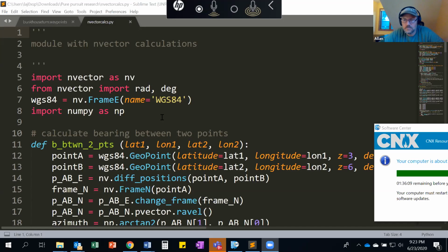In UAV land, we had waypoint navigation that was somewhat like path. We had a waypoint capture mode. If you got so close to the waypoint, it would capture it so it wouldn't circle back and try to fly that waypoint again, because it's sometimes harder if you have strong crosswind and other things fighting you in the air, right?